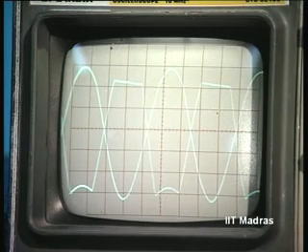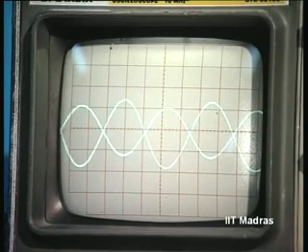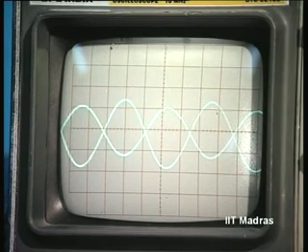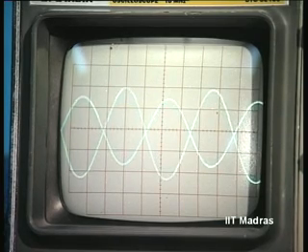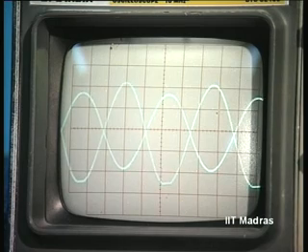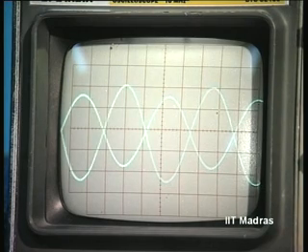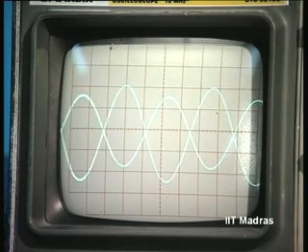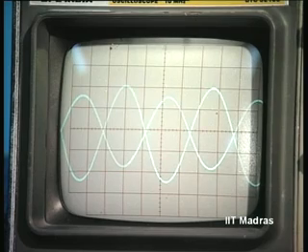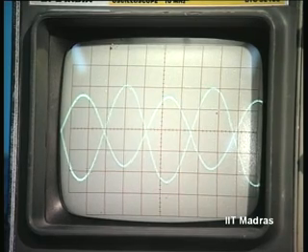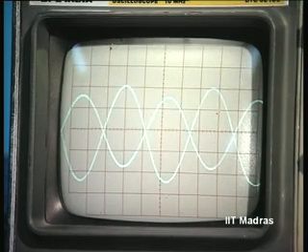Reduce so that it just enters nonlinearity. We keep on increasing the signal further, just stop there. Now the peak to peak signal is a limit that you have not really obtained earlier, because the input signal is also going to reduce the output swing. Input is increasing when the output is decreasing. This is the signal swing. This kind of signal evaluation we will be doing again later when we discuss negative feedback circuits.